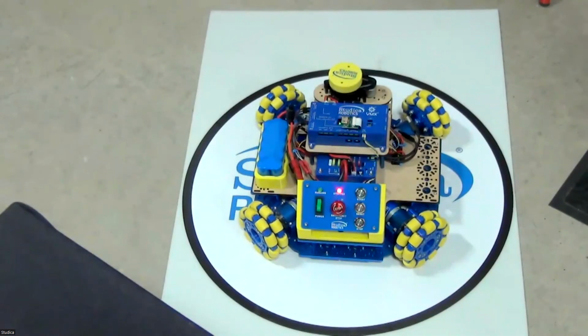If I stop sharing so you can see better, notice how the stopped LED is lit up because the robot is not enabled and it's not moving. You'll also see the Titan is flashing green, red, blue. This shows that it's detected the CAN signal, but the robot is disabled. If I were to enable the robot now, you can notice that the running LED is now flashing, which is telling me that the robot is now running. I can also see that the Titan is flashing purple, which is showing that it's enabled as well. So now I have two ways of seeing that the robot is running and is live.